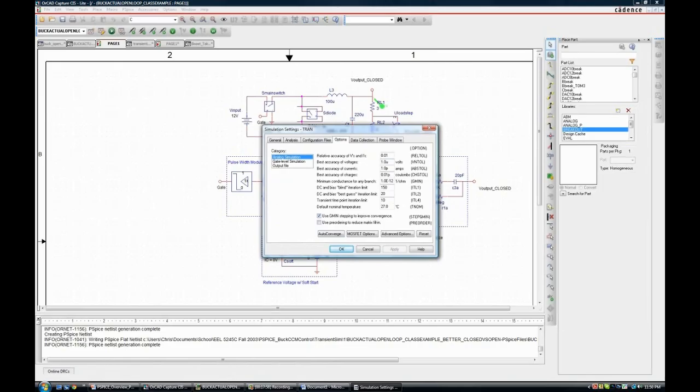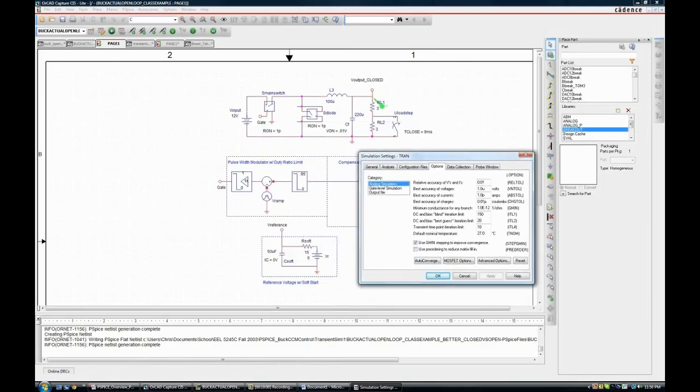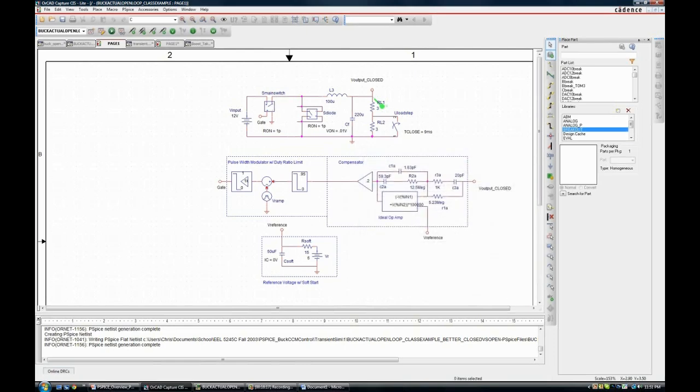The most effective thing you can do when it comes to improving convergence, especially in power electronic circuits, are the virtual snubbers that I just described, by putting caps across these points or to ground, or adjusting RELTOL from the default value of 0.001 to 0.01. Okay, so that's basically autoconvergence in this control system, and it's interesting to note how fantastically the closed loop control improves the response.